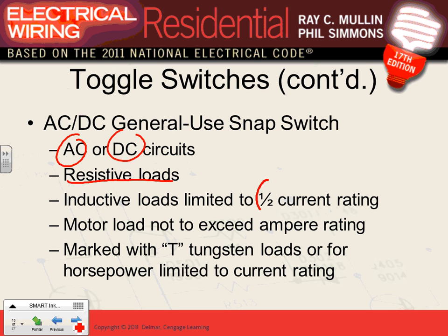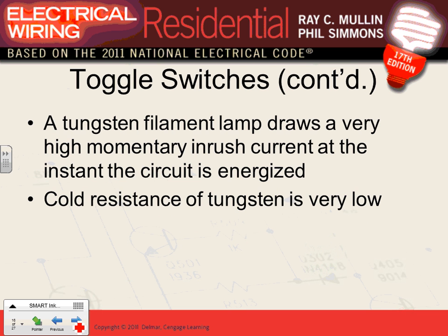Inductive loads, you have to cut it by half. You have an inductive load like a motor, you have to cut the load by half. And motor load not exceeding the ambient temperature rating, and marked with T for tungsten load for temperature rating too. So there are some limitations.